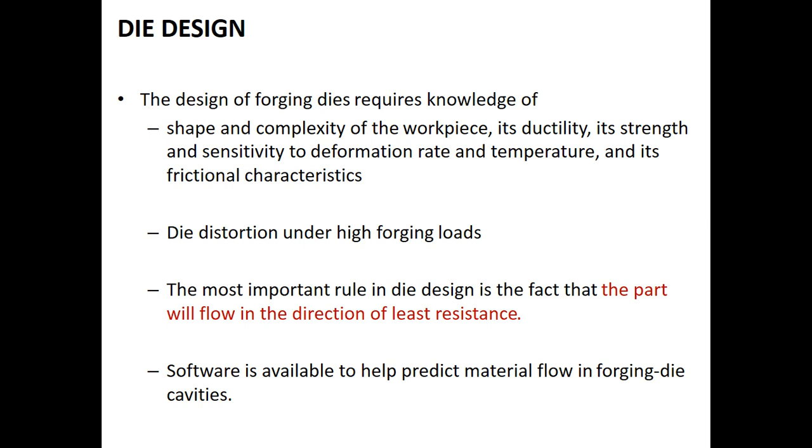So in the design of forging dies, a designer should have a thorough knowledge of all these aspects, and at the same time he or she should be familiar with the distortion of the die under high forging loads. So when the die is subjected to high forging loads, how much deformation it undergoes.